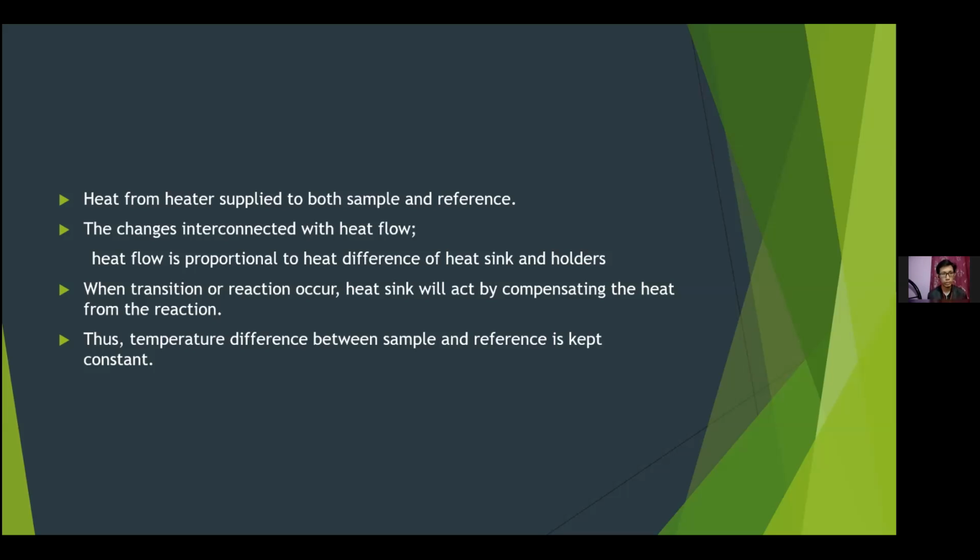Thus, the temperature difference between the sample and the reference is kept constant. In the sample and reference, the difference in amount of heat supply is relative to the temperature difference of both sample and reference holder. The quantitative measurement of an unknown sample can be done by calibrating with a standard material.